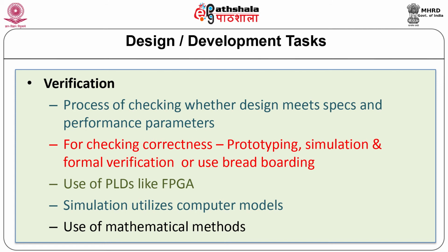One can physically build the circuit using discrete components rather than ICs. This common practice is known as breadboarding. It is also possible to use programmable logic devices like FPGA for prototyping. The advantage of prototyping is that it provides real-time behavior of the design.